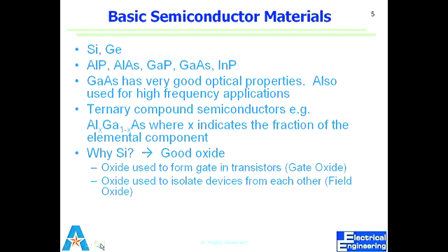So these are major uses of silicon dioxide. Two most important uses: gate, which is, I drew that transistor last time. There was this part where you had to have an insulator layer, and you apply some voltage on top of that, which results in accumulation of charges, which connect source and drain. So there is a path of travel. That is where we want to use oxide called gate oxide. And the other, field oxide, where we want to isolate electrically active devices from each other.